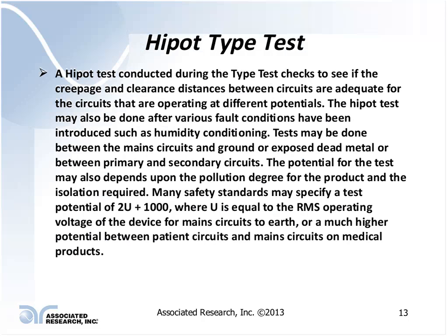Many safety standards may specify a potential of 2 times the voltage rating of the product plus 1,000 volts, which is equal to the RMS potential of the device.